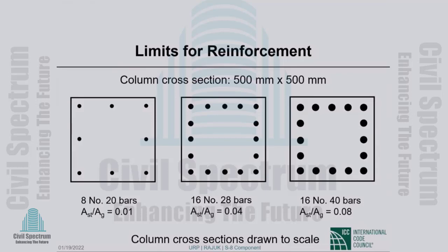remember, very importantly, we haven't discussed this yet. I hope to do it in non-seismic detailing. These column bars have to be tied and cross-tied. Okay? There will be one tie all around, and then every other bar, this one and that one, has to be laterally supported by a corner of a tie or a cross tie.